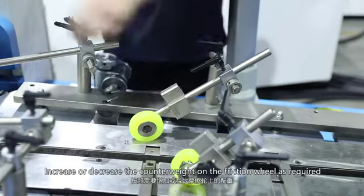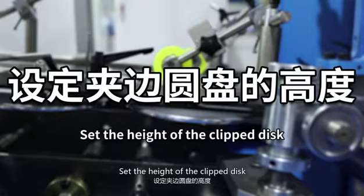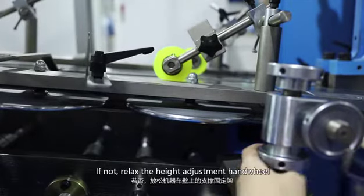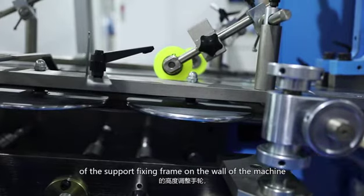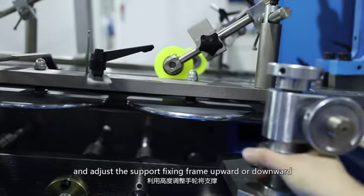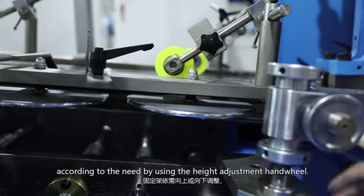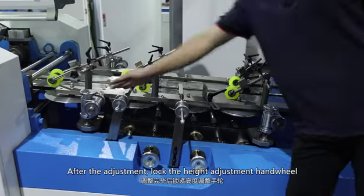Increase or decrease the counterweight on the friction wheel as required. Set the height of the clip disc. Check whether the clamp disc is in the center of the two forming templates. If not, relax the height adjustment hand wheel of the support fixing frame on the wall of the machine and adjust the support fixing frame upward or downward according to the need by using the height adjustment hand wheel. After the adjustment, lock the height adjustment hand wheel.